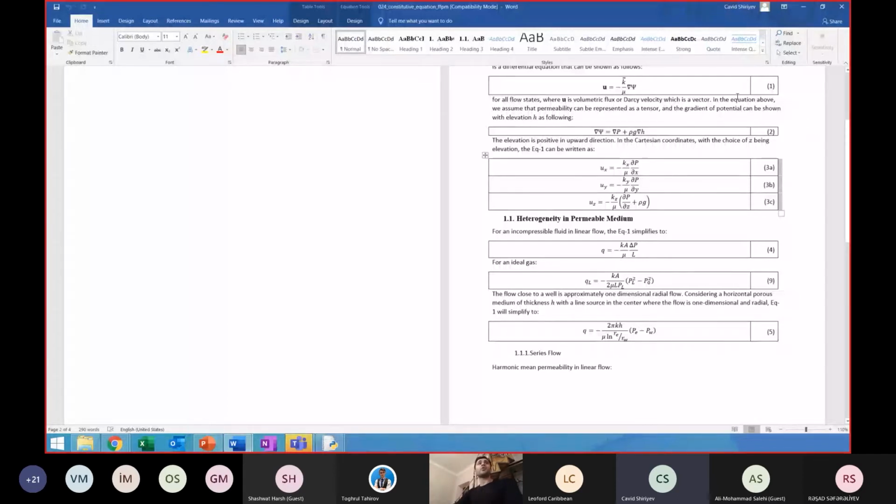Now, talking about the equation of state, that's the last thing we need to know for our single phase solver. So let me open the proper file for that equation of state. Now, we are talking about the slightly compressible fluid. Okay, if we have the incompressible fluid, basically we are solving the Laplace equation, and in this session we are going to see the Laplace solution for the given one-dimensional problem, one-dimensional domain.